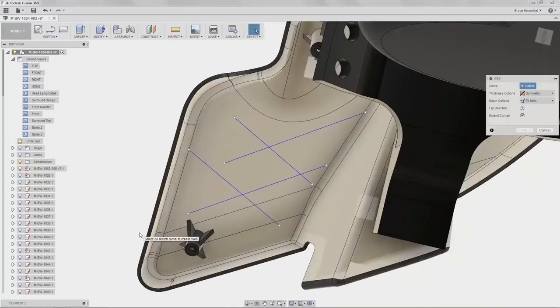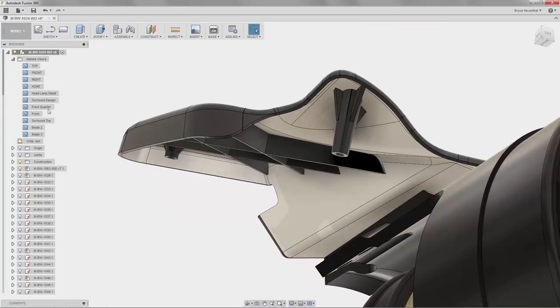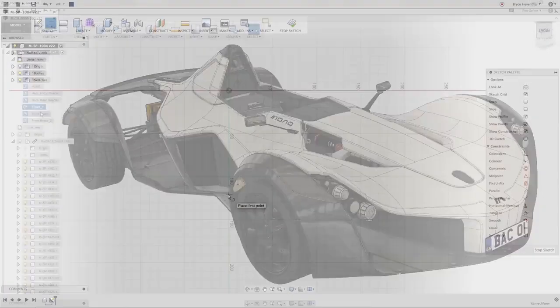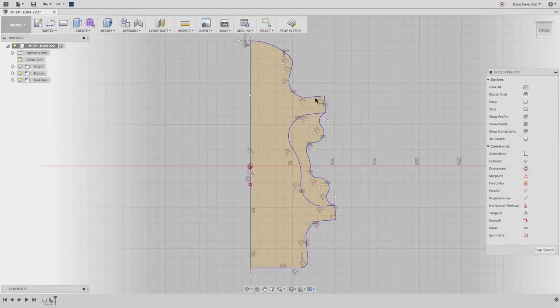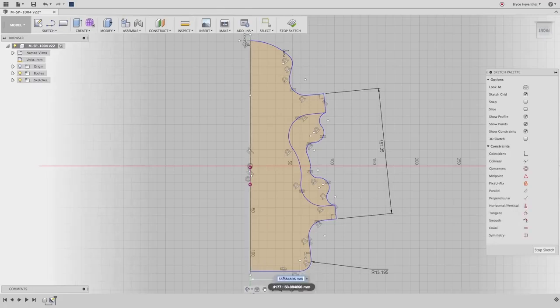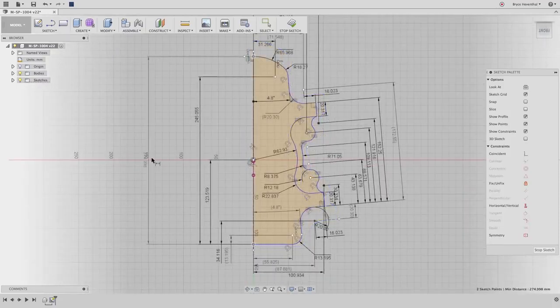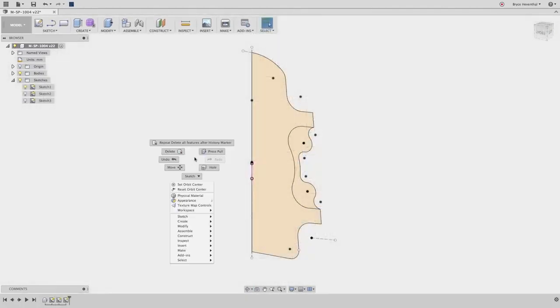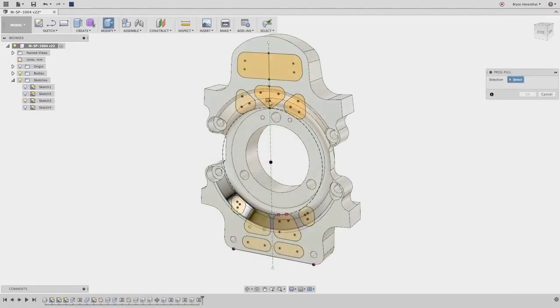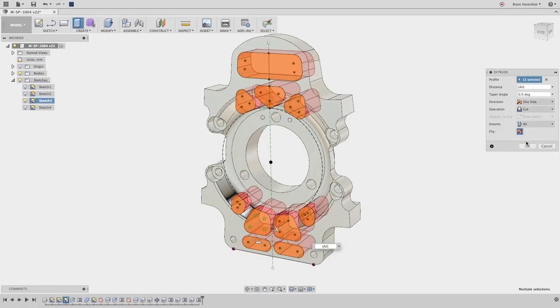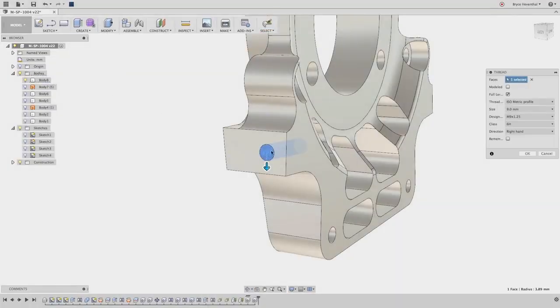Once you get the shape you're looking for, this shape is treated just like any other body or component in Fusion 360. Now, when it comes to engineering a product, having parametrics is essential to ensure the location and size of your features are correct. Many of us who have used other CAD tools understand the benefits of solving the design mathematically, knowing that changes need to propagate throughout the rest of the design via parameter relationships, so of course we put this into Fusion 360. Start by setting up your sketches, drive them with constraints, parameters, or equations, and then turn that 2D sketch into 3D geometry. In this mode, features are captured in time, making it a piece of cake to make changes to geometry when that inevitable design change occurs.